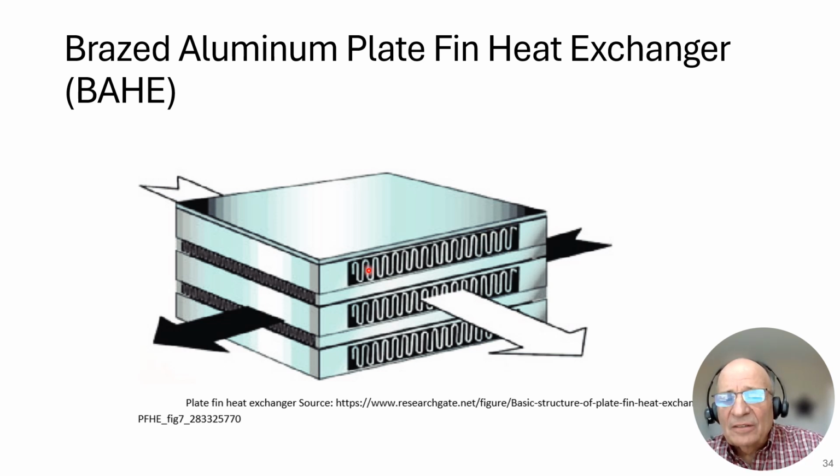And in one set of fins, you'll have one flow going, another set of fins, you'll have another flow going. These can be made counterflow, cross flow, multiple passes, very complex exchangers, and they are compressed together. They're constructed, very accurately machined and closed together, and in between each seam is some flux and some braze material. The entire compressed unit is then submerged in a molten bath. The braze material melts and adheres to the aluminum, it's taken out of the molten bath, and then allowed to cool.